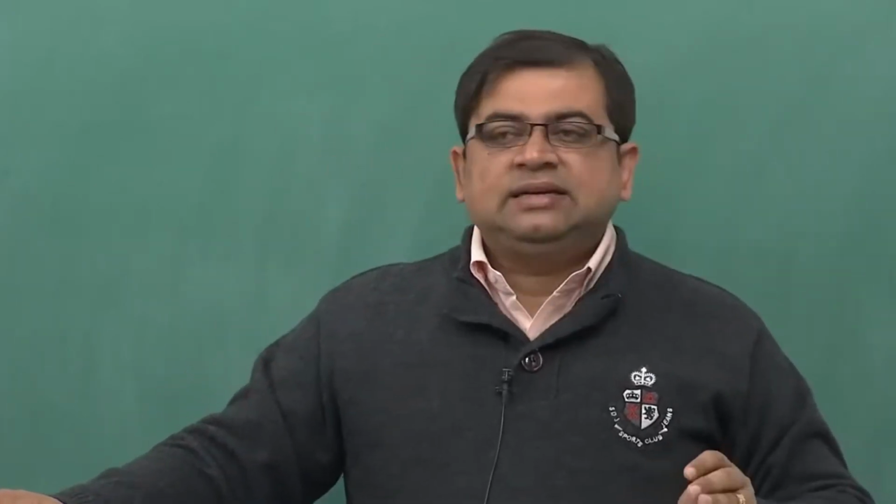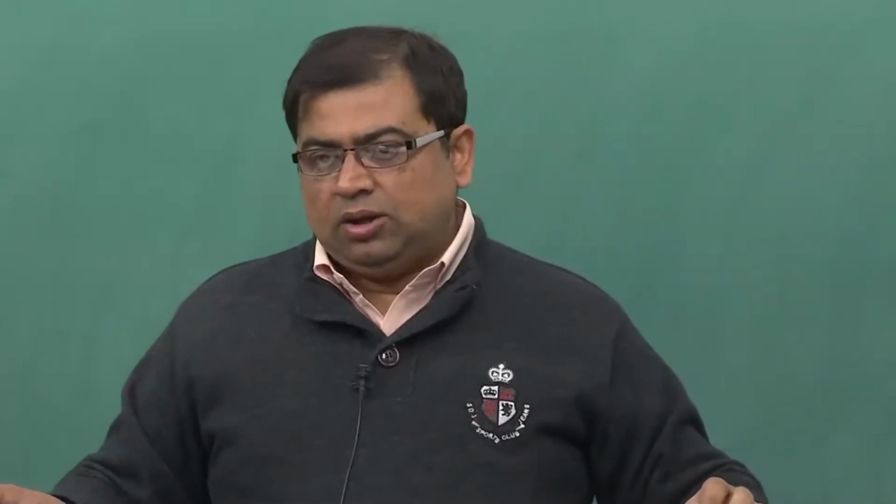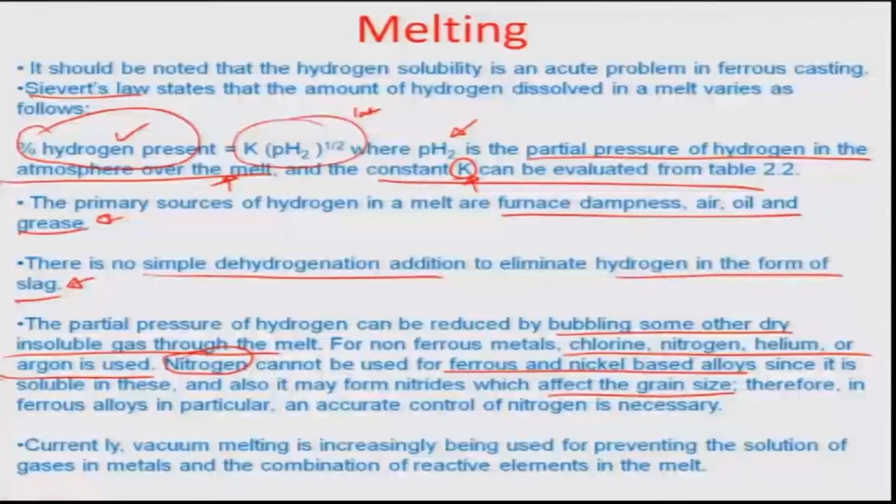So, there is an increasing trend in the industry of doing vacuum melting nowadays. So, you do not really bother about the various gases, because you have outgassed the furnace before you have started the melting process, and so this is being increasingly used, although it is expensive, and it has to really be a smaller furnace, and it cannot be applied to a very large scale melting process, because vacuuming a certain region becomes very expensive. But there is an increased utility of vacuum based melting methods for producing melts.